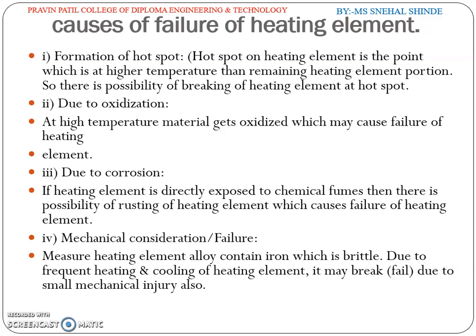So the causes of the failure of the heating element will be due to corrosion, due to oxidization, then mechanical failure, where the heating element alloy contains iron and is brittle.